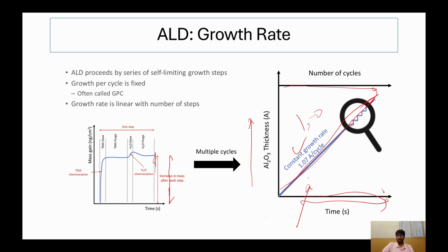So sometimes people get 1.1 angstrom per cycle, or 0.11 nanometer per cycle, 0.1112. That depends on your process parameters. Mostly you get around 0.1 nanometer per cycle. Sometimes, because of stresses, compression or elongation stress, the bonds may vary a bit. That can happen.